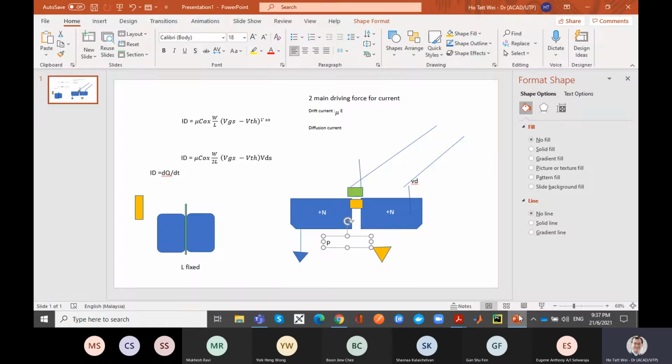Okay, and when you have a capacitance across the diode, everywhere along here, in the source and the drain, there is a capacitance to the bulk, the p-type bulk. And everywhere along here, there is a capacitance from the drain to the p-type bulk. So there are two sources of capacitance at the source and at the drain. One is the gate to source, gate to drain capacitance. One is the drain to bulk, source to bulk capacitance. And this is called a depletion capacitance because it arises from a depletion layer, because of the N and the P type here. There's an implicit diode formed here.